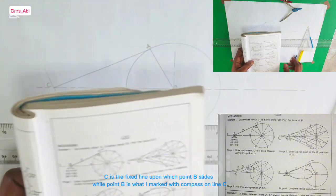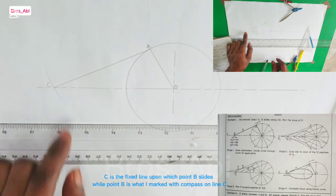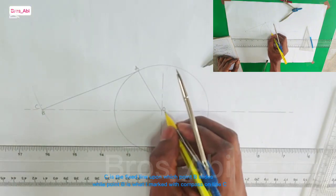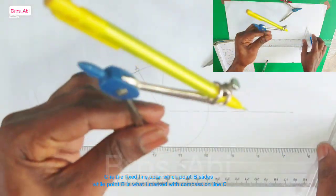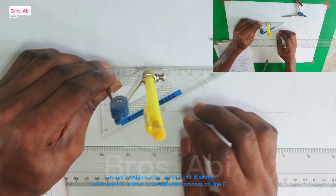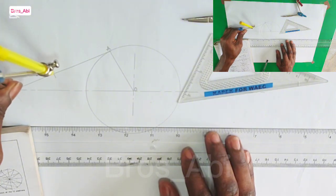Now point P is 40 millimeter away from point B. Here's point B, and this line to here is line CO. Now I'll open my compass to 40, since this one is already 95. I'll put it here and mark.